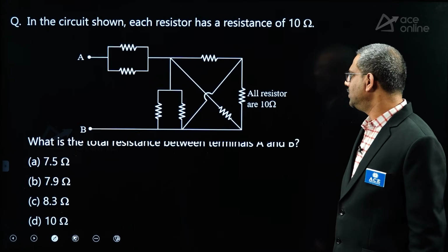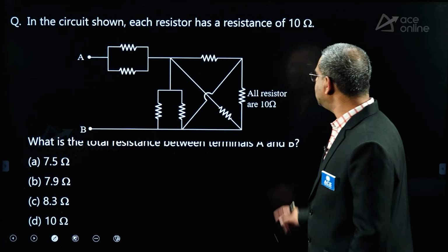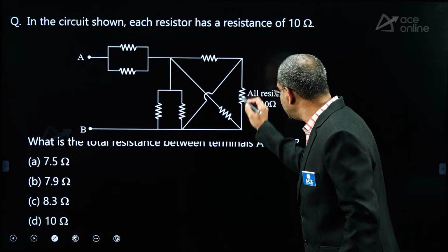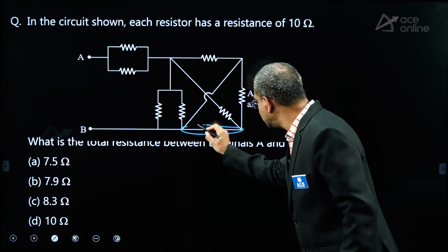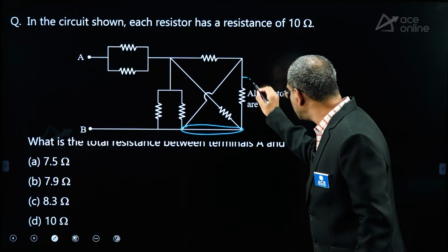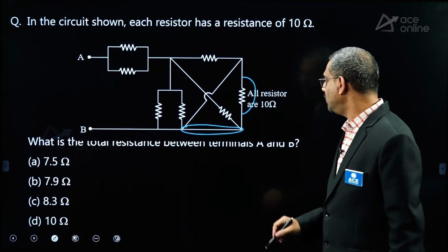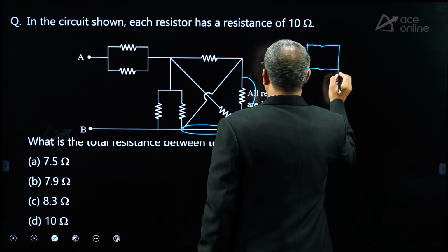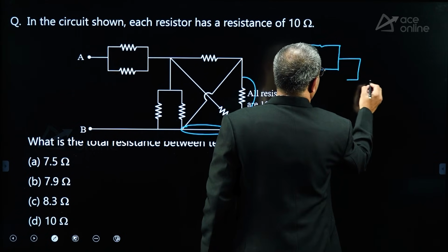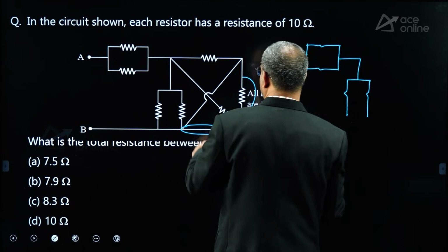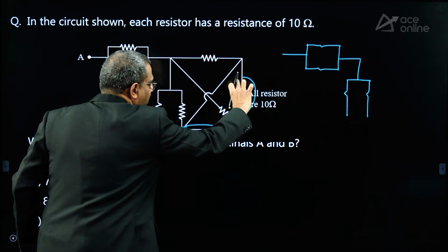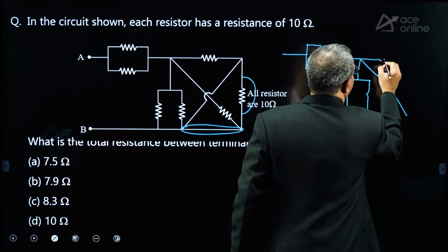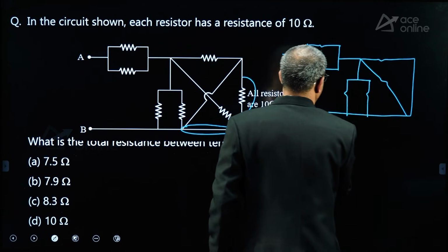Okay, simple Ohm's law. Now he is asking the equivalent resistance where each branch resistance is 10. Now if you observe, sir, first of all, this is shorting this element, because this is a single node. Watch this. If this is a single node, this is shorting this element. And all resistors are 10. Now if you short this, very interestingly, this is 10, 10. That I am not disturbing. Here also this is 10, 10 in parallel, and I am not disturbing this part. But here, by shorting this, 10 and 10 become parallel. So finally this is 10 and this is 10, but this is shorted.